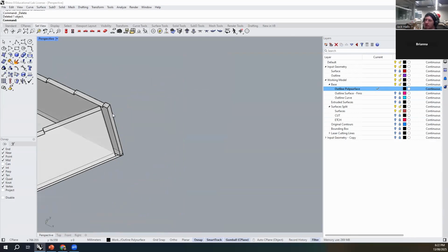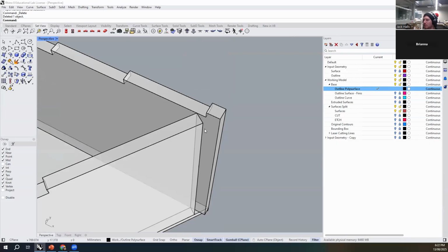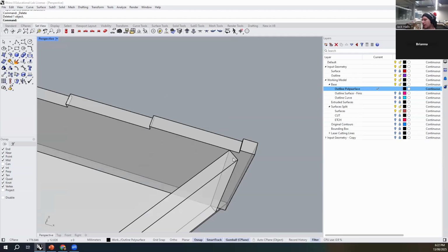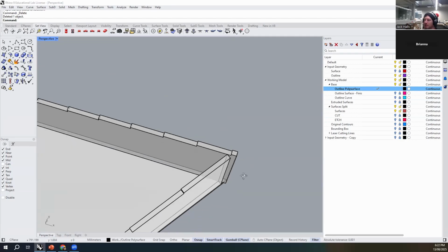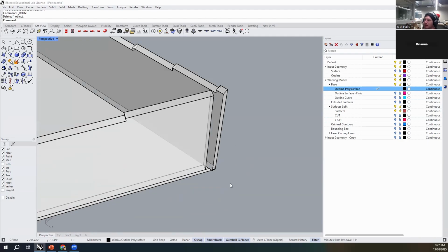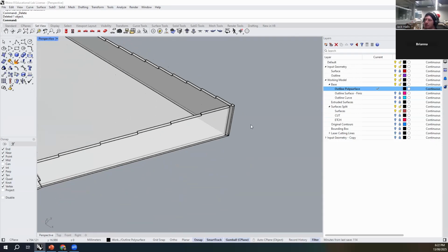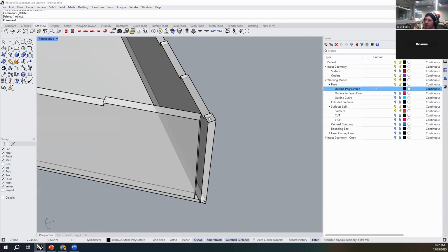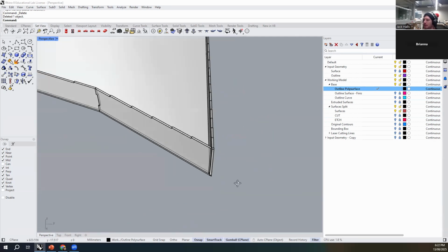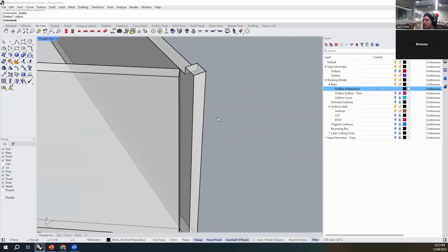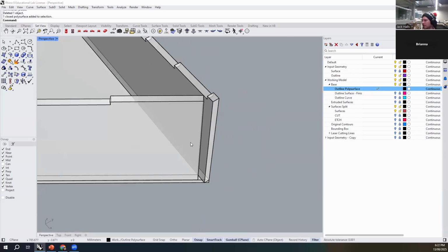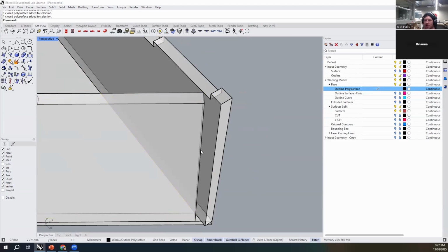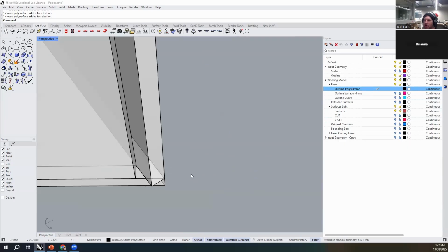Now, the reason that everything that I'm cutting off is ending in this sort of butt joint, this hard edge, and not like an angle or anything, is because that's within the parameters of laser cutting. The laser cutter can't cut angles into those edges; it can only cut straight edges from the top face downwards. Okay, it can't see underneath things, and it can't cut downwards. So it kind of looks like that's a disjoint edge, but when you think about how thin these materials are, some glue in that edge is going to make it reasonably strong.